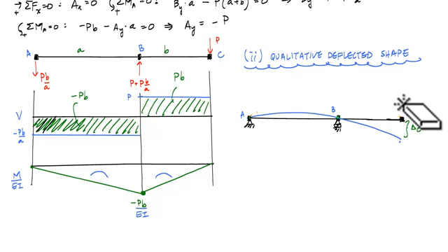This beam is not symmetric. I don't know where there's a zero slope. The loading is not symmetric, the boundary conditions are not symmetric, and there's no fixed support to tell me where I have zero slope. I do know that I have zero deflection at point A and zero vertical deflection at point B. So this problem is a little more challenging only because we have to use additional geometry relationships plus the moment area theorems to solve for this deflection at point C.